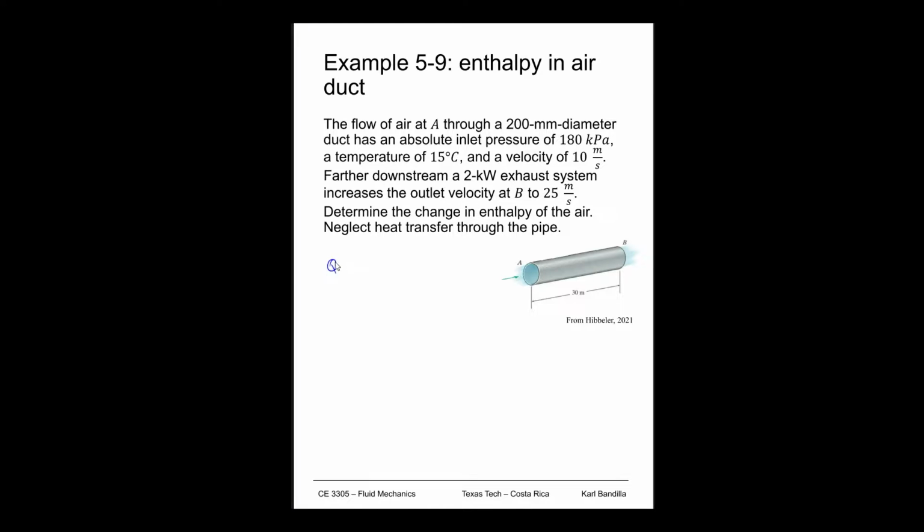So we have Q in, right? That'd be the heat transfer plus any energy added by a pump minus any energy that a turbine might be taking out. And all that is equal to the enthalpy at the outlet point plus V out squared over 2 plus g times z out.